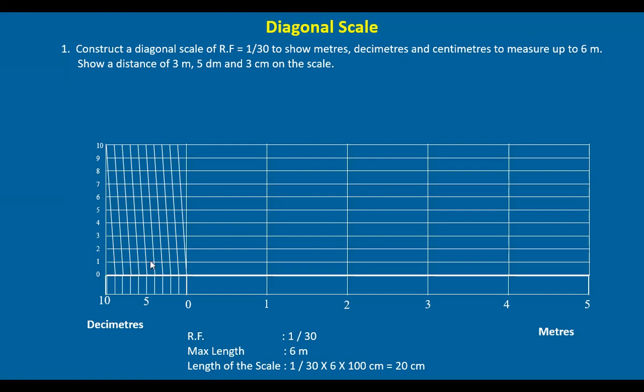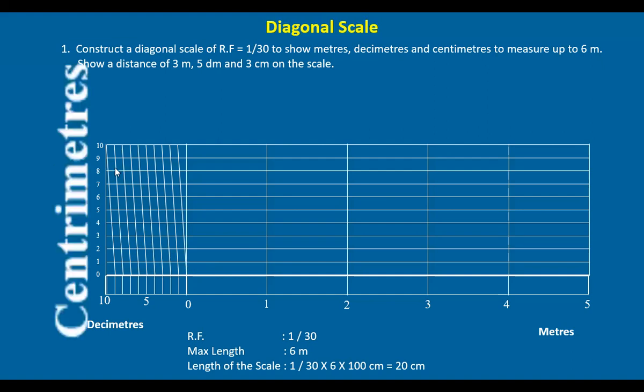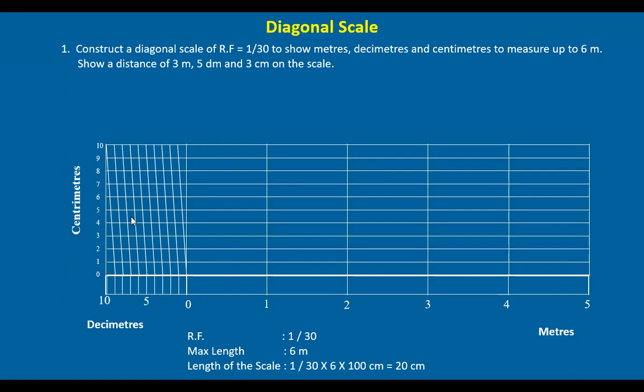Now, through point 1, we have drawn a horizontal line. And if you see this distance between this inclined line and this vertical line, this distance gives 1/10 of this length. This length is nothing but 1 decimeter. So 1 decimeter divided by 10 means 1 centimeter. This length actually gives 1 centimeter. That's how we get centimeters here. We are able to measure 1 centimeter also.